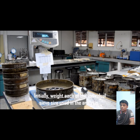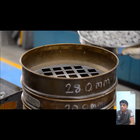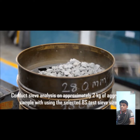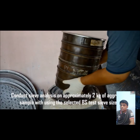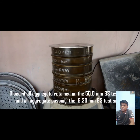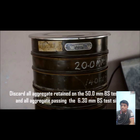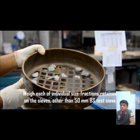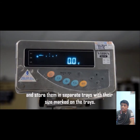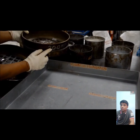We weigh each individual sieve size using the analysis. Secure a representative sample of aggregate and put it in the sieve. Conduct the analysis of a 2 kg aggregate sample using the selected BS test sieve sizes. Discard all aggregate retained on the 50.0 mm BS and aggregate passing the 6.30 mm BS test sieve. Weigh each individual size retained and store in a separate tray marked with its size.